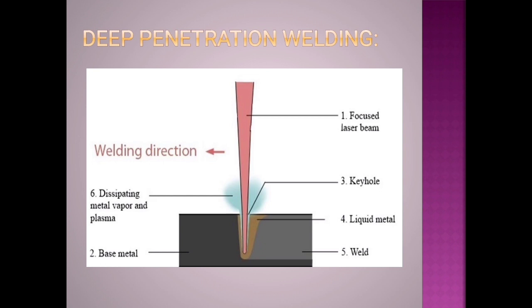Still, laser beam welding has many advantages over electron beam welding. They are: the laser beam can be transmitted through the atmosphere or through various gases without excessive attenuation, whereas the electron beam suffers from this disadvantage because vacuum is essential for operating electron beams. With the laser, tooling is rather simple. In laser devices, a mirror can deflect the laser beam close to the focal point.